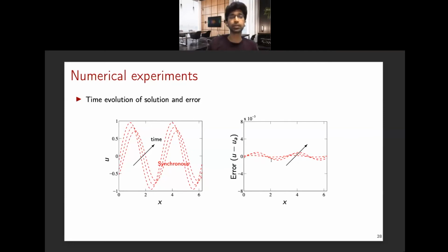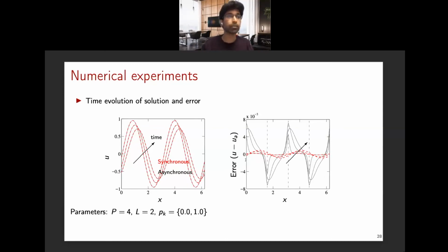So now let's do the same thing. This has been done in a synchronous fashion, the traditional way of computing things in all the PDE solvers, where you wait for the communication to finish and then go ahead and perform the computations. Now, in the next step, I perform asynchronous simulations. That means we don't wait for the communication to finish. We take the values to be whatever they are in the buffer points and then go ahead and compute. These can be synchronous values or the delayed values.